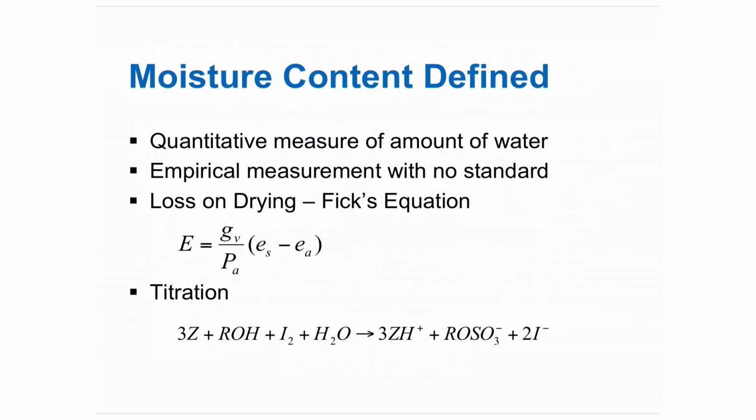It is possible to do that with water activity. You simply use a salt solution of a specific concentration or at saturation, and those water activities are known because they're determined or dictated by thermodynamics. So I can take a sample of a salt solution, put it in a water activity instrument, and beforehand know what the right answer is, and then determine whether the instrument provides that correct answer. That being the definition of accuracy, and whether or not you hit the bullseye or hit the right answer.